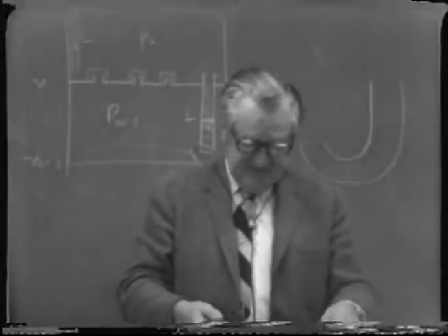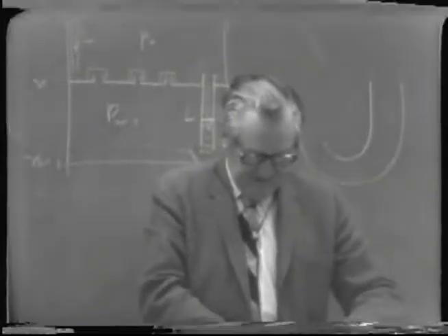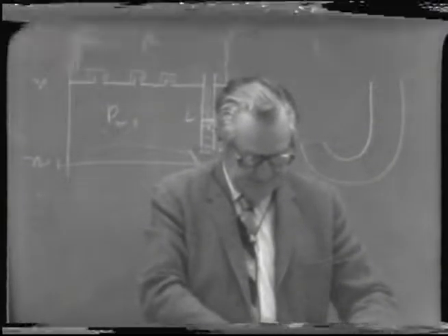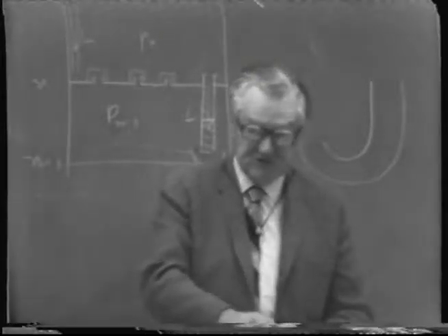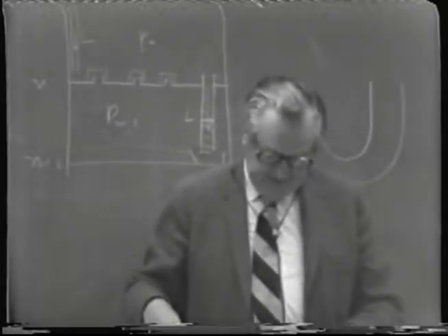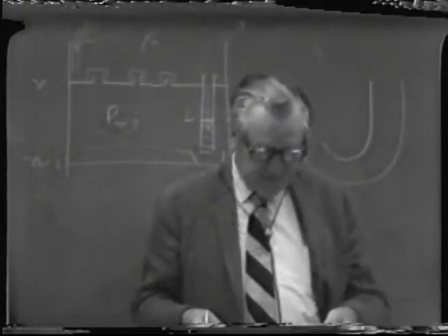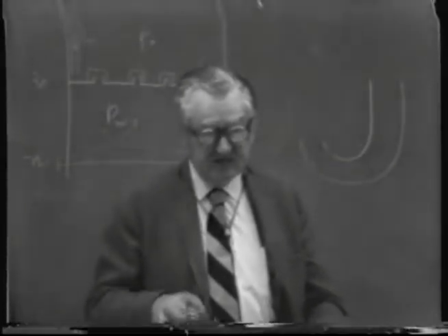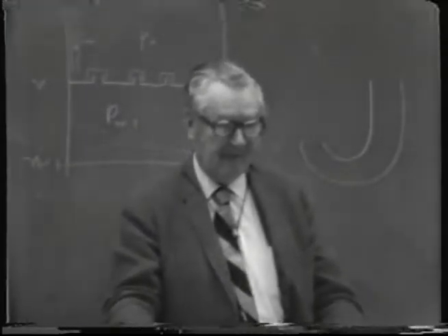And as we've seen in our McCabe-Thiele problems, the temperature has some effect on the ease of separation too. But nevertheless, from the standpoint of pure economy, it'd be desirable to get as much heat out of that stillage as possible.